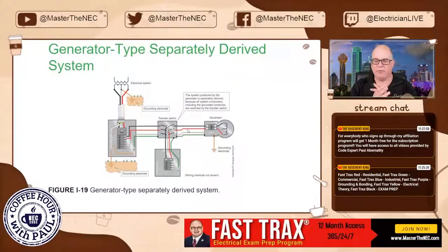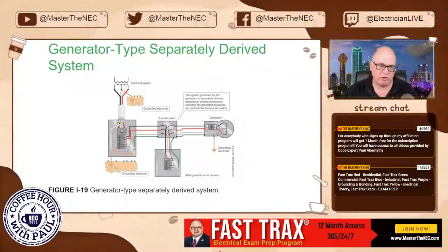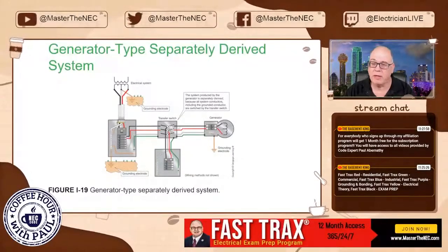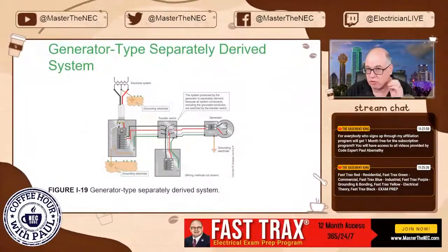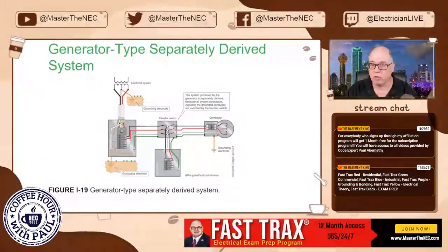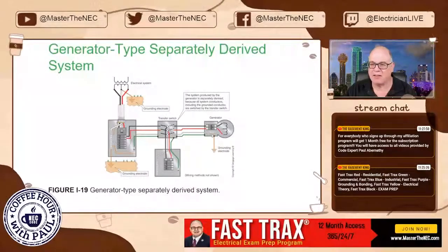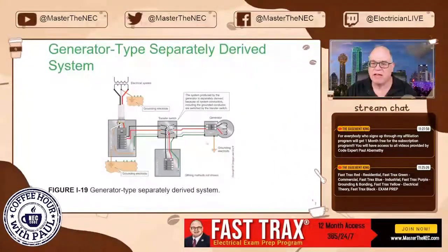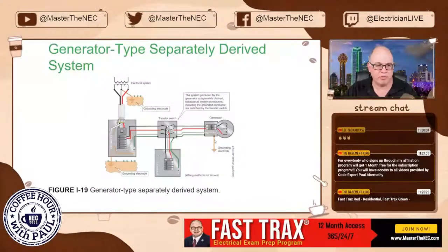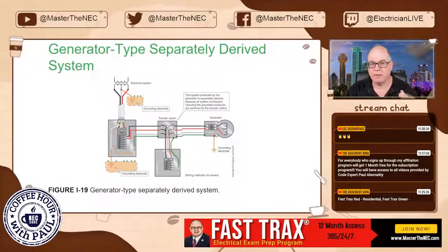Be very careful, because I was part of a case years ago where the equipment came with this system bonding jumper installed, but they did not switch at the transfer switch, did not switch the neutral. And what happened is you had this system bonding jumper installed, and you had circulating currents on the metal parts, and created a hazard, and a person got hurt. Okay?